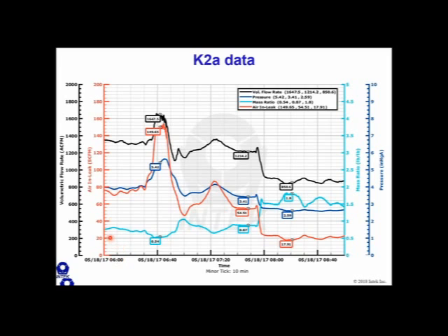We arrive on site and we can clearly see the water to air mass ratio is below 3. It's at 0.5. So we have a problem with one of them, either air in-leakage or vacuum pump capacity. If you recall, 1,400 cubic feet per minute was a good flow rate from those vacuum pumps. And so when we arrive, we can see that the vacuum pump is pulling about what we would expect.